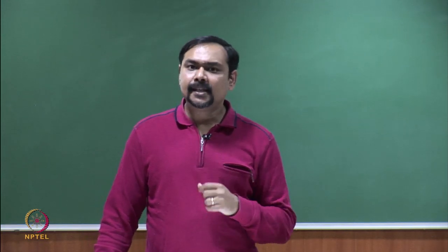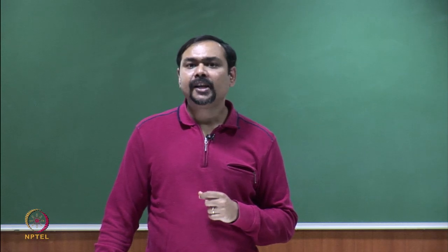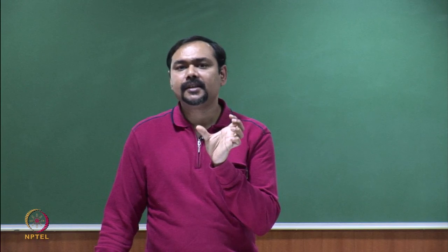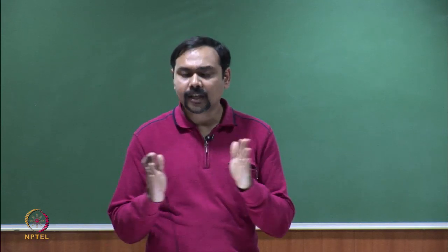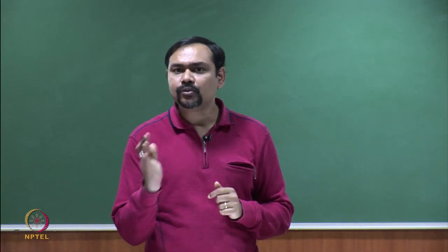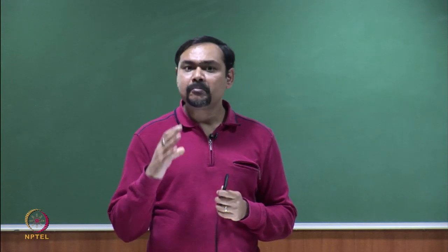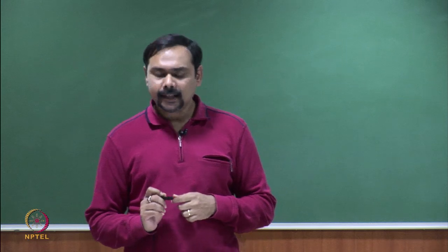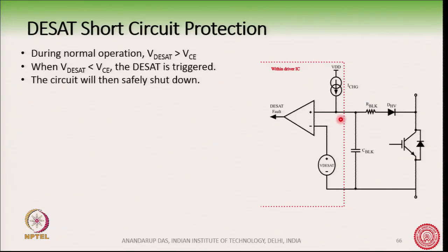So, this delay should ideally be at least the delay for which the IGBT is turning on, that is the total time delay of stage 1 to 4, that much delay must be present, if not more. That delay is provided by this RC circuit here along with a charging current here.